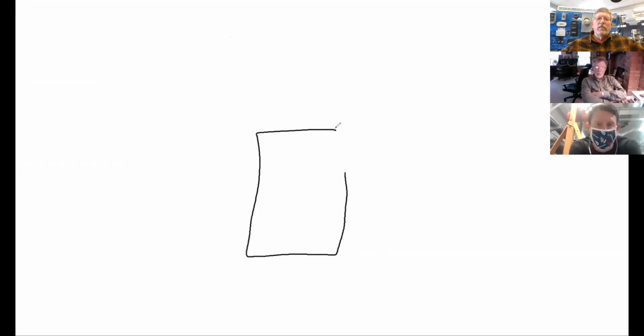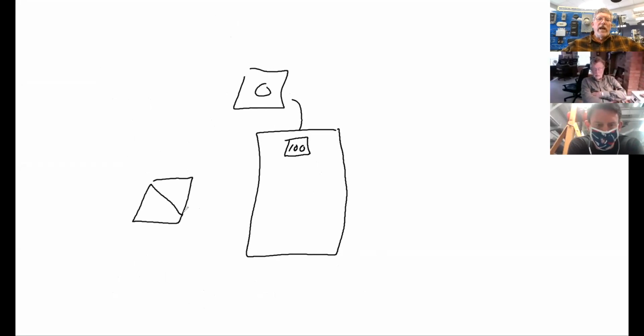So what we're talking about here is, let me clean this up. We're basically saying, okay, we've got a service panel here. Here's your main, and it's coming in at 100 amps. That's going out to your electric meter. And we've hooked in an inverter. Remember, the inverter has to be hooked in at the furthest point from the main on the bus bar. So we want to hook it up down here in the lower left-hand or the lower right-hand corner.